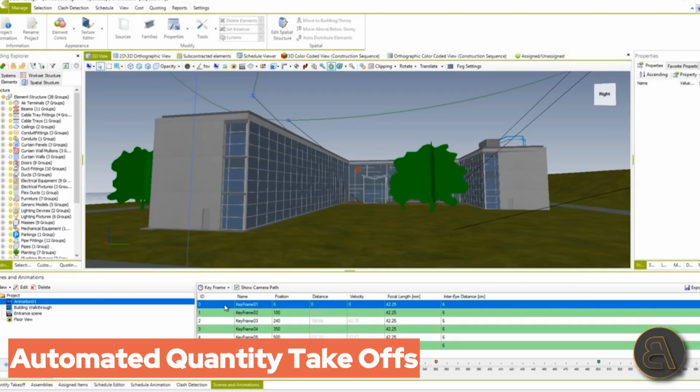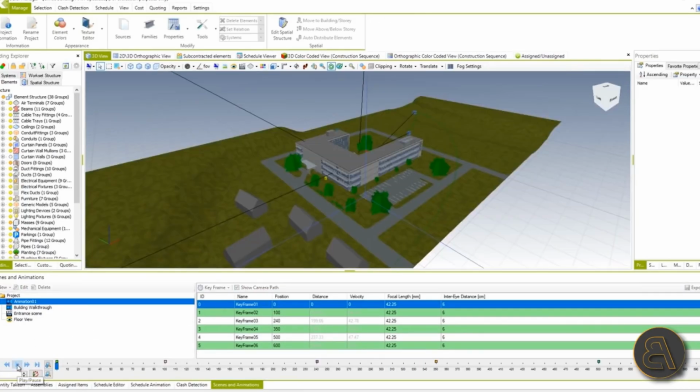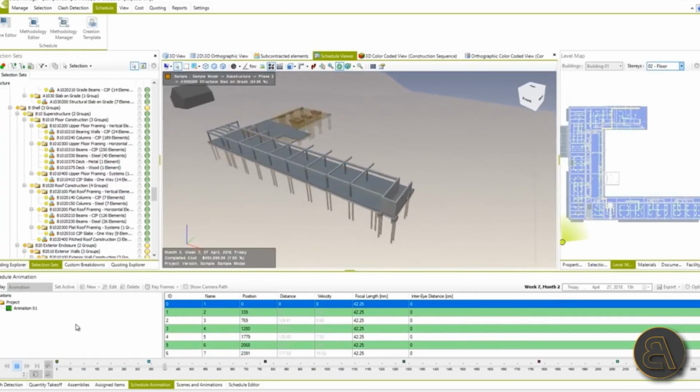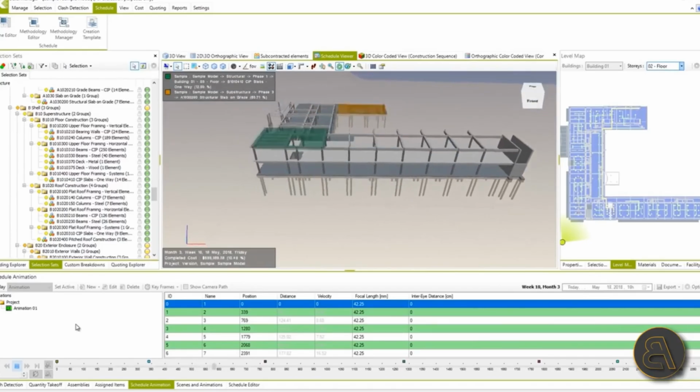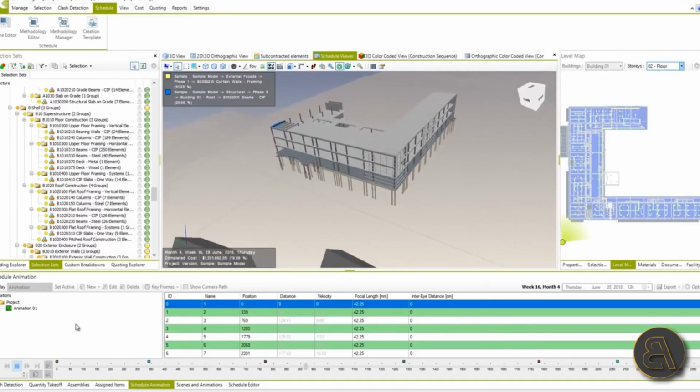Now let's move on to 5D BIM that adds costs into the equation. That means automated quantity takeoffs. Models calculate materials and quantities instantly. Cost integration is included as well, so materials, labor, and equipment costs are linked to every model element. Then we have dynamic budgets. Any design change updates your cost data immediately and in real time. The popular tools used for 5D BIM are BEXEL Manager, CostX, and Candy. Integrations with Revit and Navisworks are also common for quantity and cost workflows.